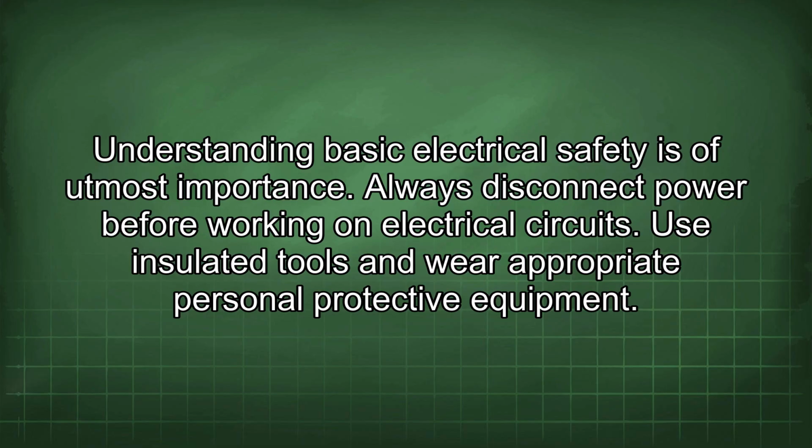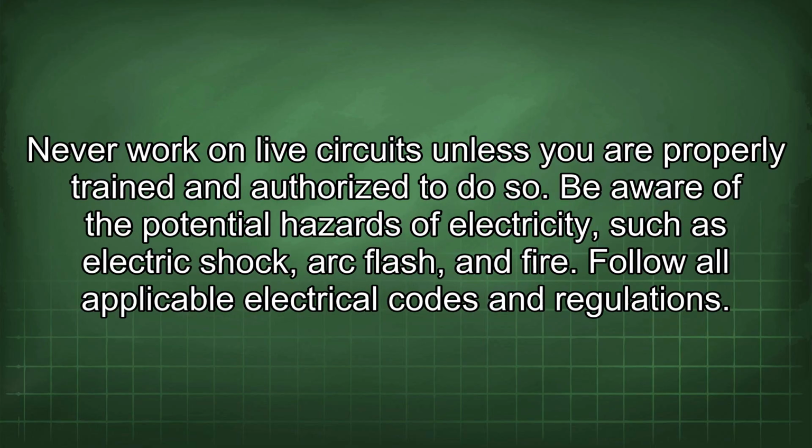Understanding basic electrical safety is of utmost importance. Always disconnect power before working on electrical circuits. Use insulated tools and wear appropriate personal protective equipment. Never work on live circuits unless you are properly trained and authorized to do so. Be aware of the potential hazards of electricity, such as electric shock, arc flash, and fire. Follow all applicable electrical codes and regulations.